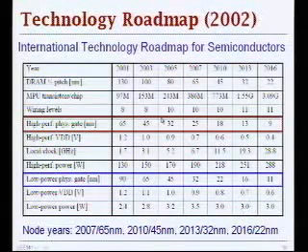And then the difference in scaling the supply voltage for the high performance and low power devices is that, surprisingly, supply voltage will be scaled more aggressively going forward in the high performance scenario than in the low power scenario. And this is just a prediction going from today's values of about 1 volt for 90 nanometer.